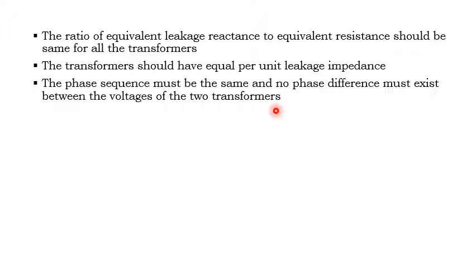So here some points are common. The polarity of both the transformers should be the same, the ratings are the same, the X by R ratios are the same, and the leakage impedances are the same. These points are the same for a single phase transformer and a three phase transformer.